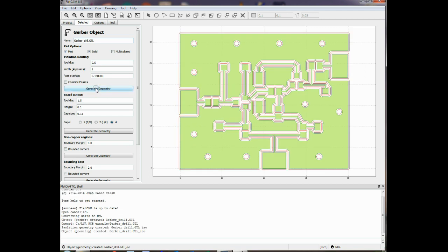Right, there we go. Now the first problem I encountered when this happened is to do with the holes. The geometry for the actual board, for the most part, is perfectly good. It was the holes that were a problem. For some reason, I actually sent a question off to the guys at EasyEDA, and I couldn't find a solution. Whenever I drop a hole or a pad in EasyEDA, and then I do the copper pour, it always generates copper pour relief, which is kind of understandable.